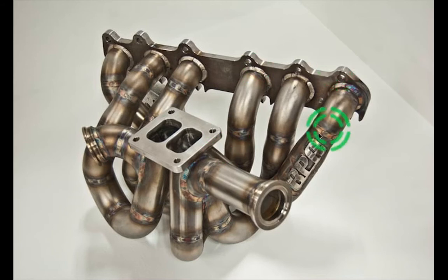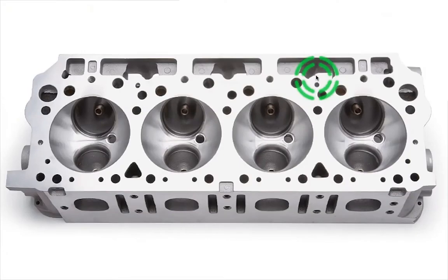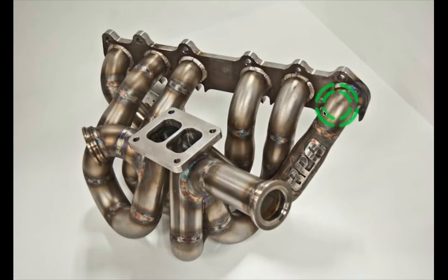The exhaust comes out from every cylinder. This one goes right here, right? So when your exhaust valve opens, it goes through this pipe to one common place, and then you have one pipe going down, which is called your down pipe. That's your down pipe. So this is a turbo manifold. Don't be shocked if yours does not look like this.